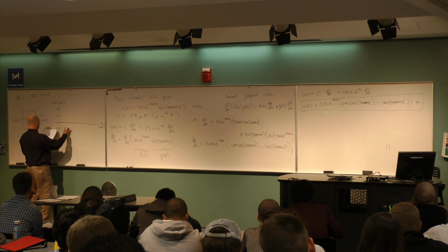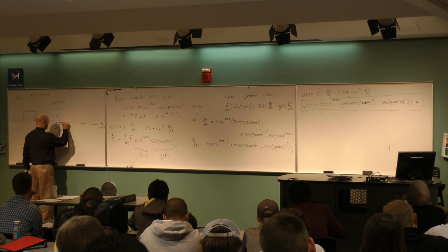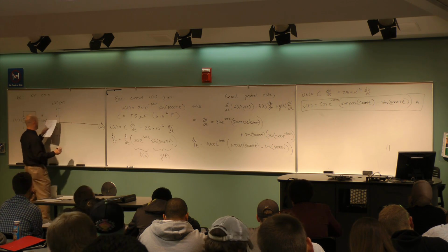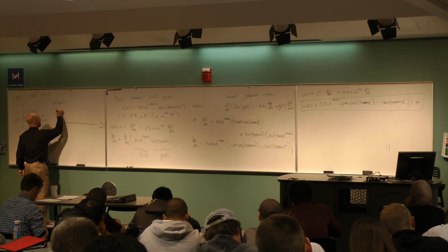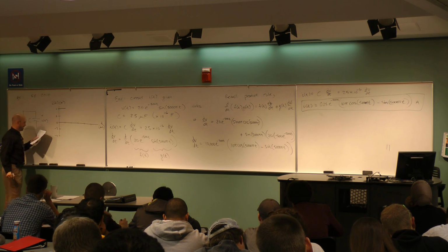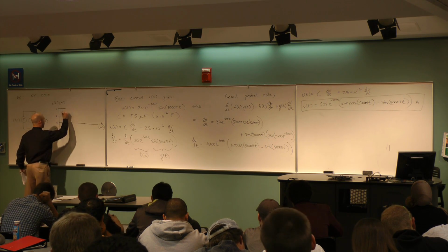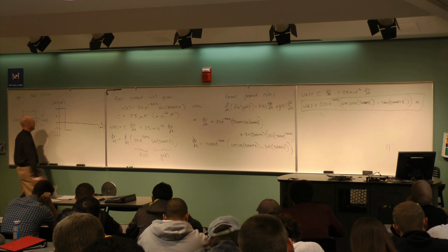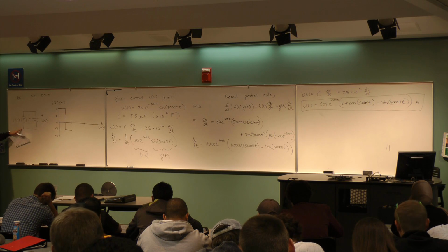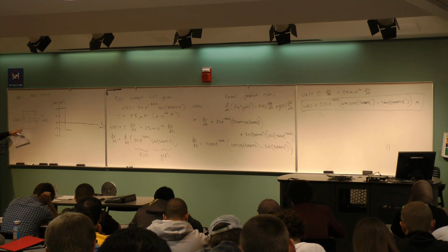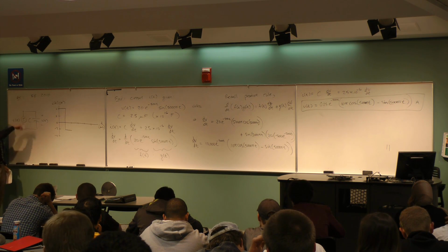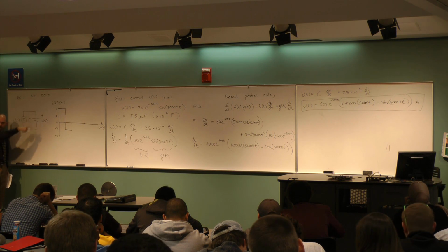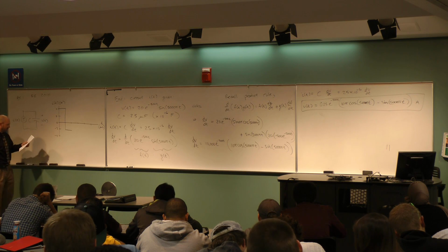So what we'll do is we'll go out for 5 milliseconds here and see what we get. For the first millisecond, we're going to be at 4 amps. Then for the next millisecond, we're going to jump straight down to minus 2 amps. By the way, what would a minus current mean in the context of this circuit? It just goes the other direction, right? So positive current flow, the way this is shown, would be clockwise. Negative just means it goes the other way.